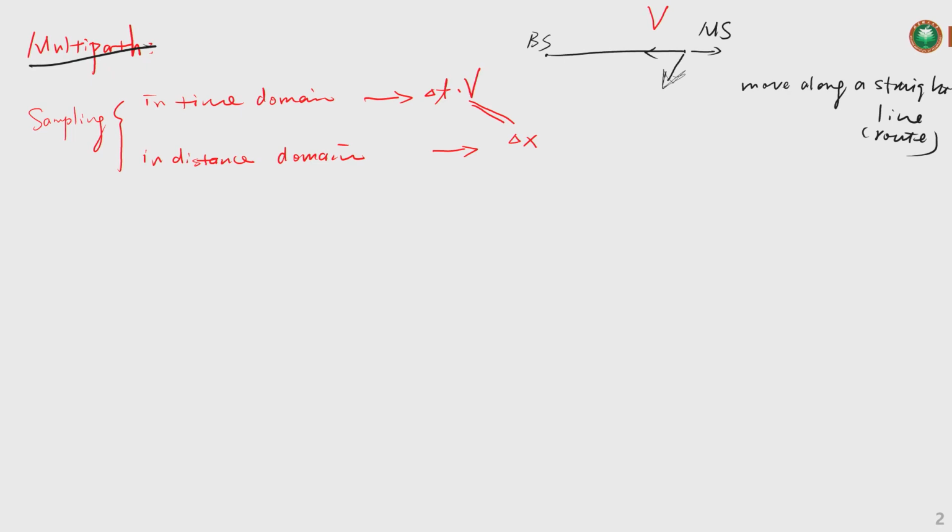But for millimeter waves or terahertz waves, we would use much more directional antennas, so a line-of-sight channel would be employed and the multipath components are reduced, because of the directionality of our antennas.